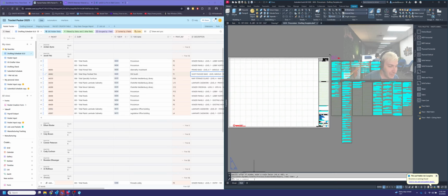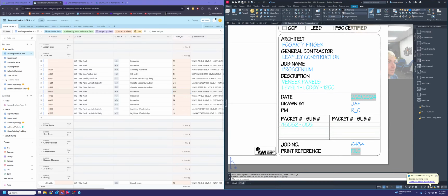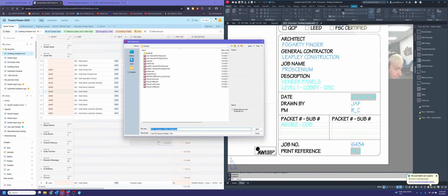Okay, so now that that's filled out, last thing before saving as, I'm also going to change my tab at the bottom to be my current print reference instead of fx.0. It should be reading p15.0 there. So right click on that tab, go to rename, p15.0, enter, and you should be set to go. So now what we're going to do is we are going to save as. Make sure to be careful not to save over your templates.